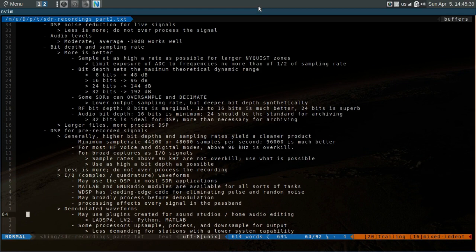There are some digital sound processing devices that will upsample the audio to 32 bits, do the processing, run all kinds of magic math on the signal, and then reduce the bit depth back to 16 bits for an output. Now, higher sampling rates and higher bit depth will produce larger files. It might be a factor depending on your hardware. If you can accommodate larger files, then certainly go for the higher sampling rates and the higher bit depths.